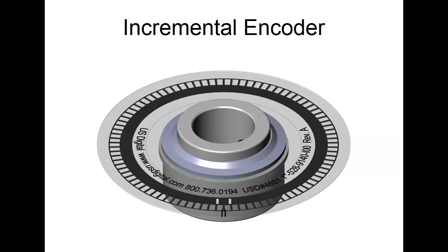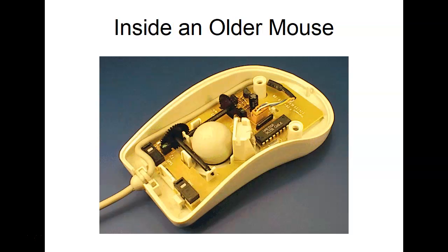So if you ever look at a robot, it's got marks on it. It's not a perfect mastering, I forgot what they call it. It's close enough, but if you want it to be exactly right, then you have to get a calibration jig and mount it on there and touch it up against something. But most of the time, we can get it within a millimeter or so. Move the robot to the marks that are on the robot, and then we tell it that that's zero. It's called some type of mastering calibration, I can't remember.